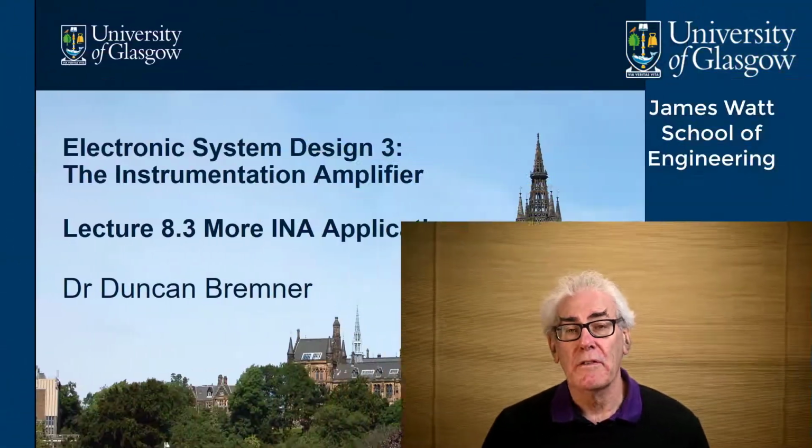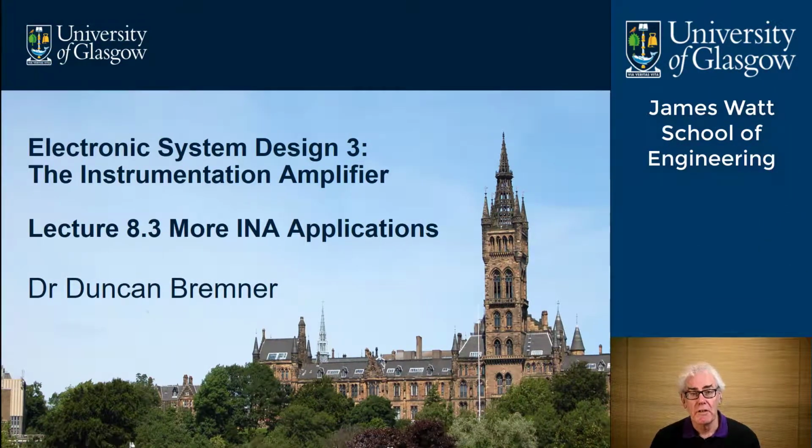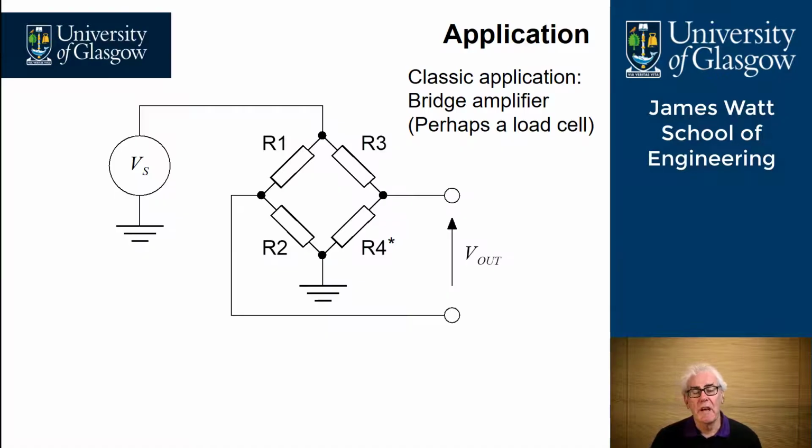In the previous lectures, we've looked at the compromises and the performance limitations you can apply to instrumentation amplifiers. In this lecture, we will look at a real application and one that will be very relevant for your design challenge. Here we have a classic application for an instrumentation amplifier. We have a load cell which consists of 4 resistors of nominally identical values.